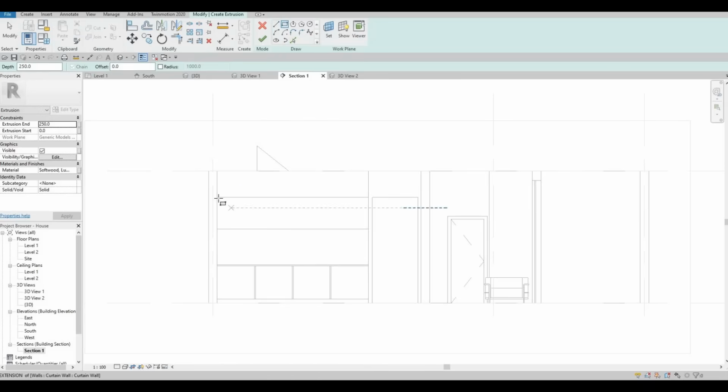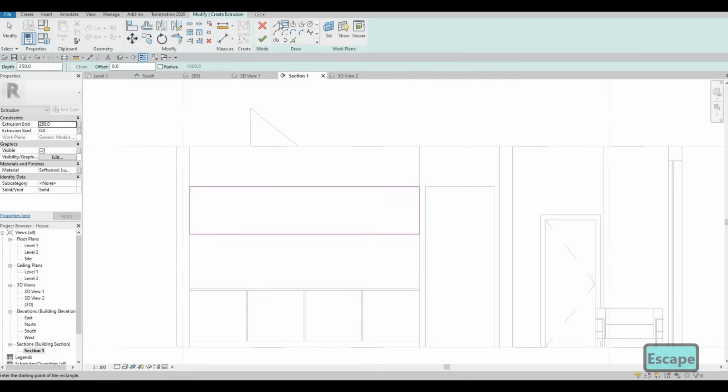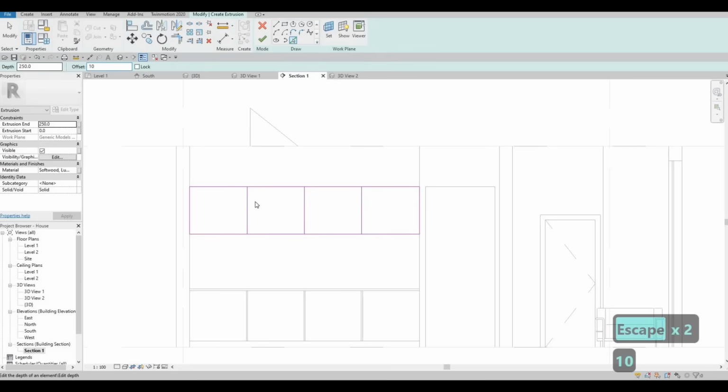Same idea, rectangle. And then after that, click on line so that you could get the midpoint. And this is same thing with this. This is around 870. So click on the pick line. This will be 870 midpoint. And then I'll pick this again and then 10.